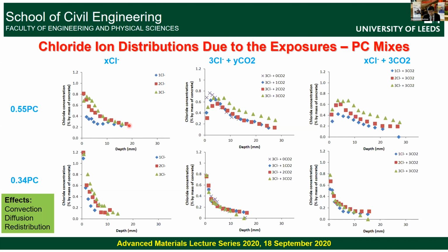Interior to the concrete, possibly not much of a difference you see for the first concrete. In here, on the other hand, the presence of carbonation or the exposure to carbon dioxide is causing redistribution of the chlorides. The surface concentration, the maximum concentration of the surface observed here has changed, and here you can see this pushing inward.